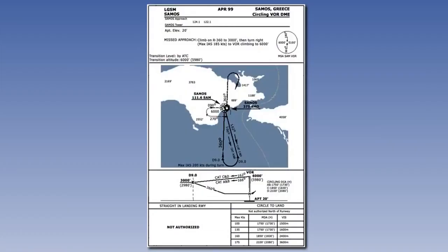We have completed our examination of straight-in approaches and their corresponding minima. Now we will turn to circling approaches and their minima. As a reminder, a circling approach is one where either the approach procedure is not aligned with a runway or is not aligned with the desired runway. In both cases, the pilot manoeuvres visually at some point during the instrument procedure to land on a non-aligned runway.